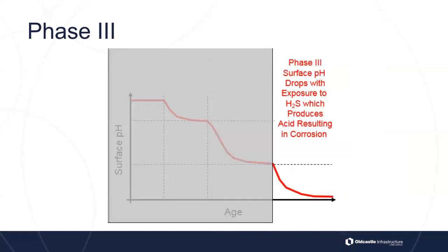And lastly, phase three, this is the deterioration phase. Okay, so this is where the real damage occurs when the excreted sulfuric acid reacts with the free lime in the calcium hydroxide and forms calcium sulfate or gypsum. Right. And so at this point, the mix design and concrete quality really comes into play. So hopefully we never get to this phase, but water to cement ratio plays a critical role here. The use of pozzolans also plays a critical role here.